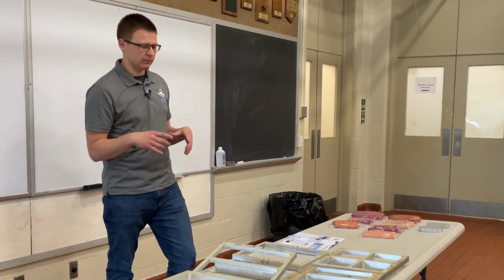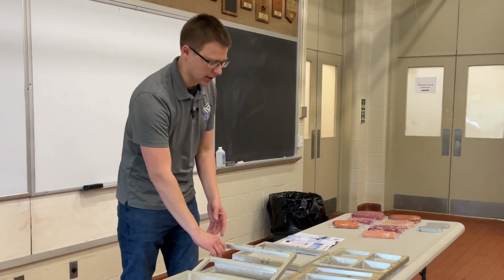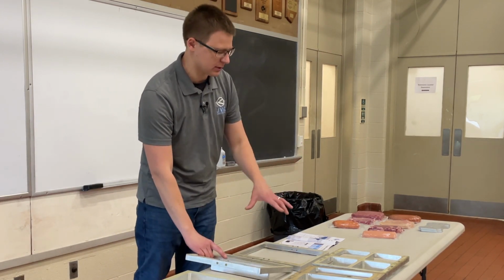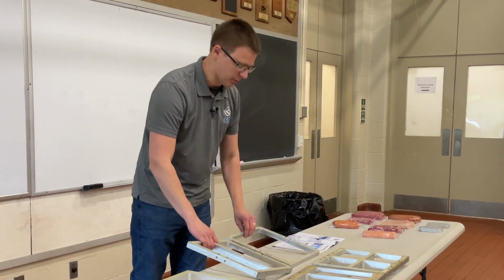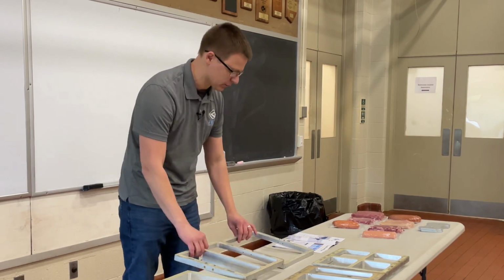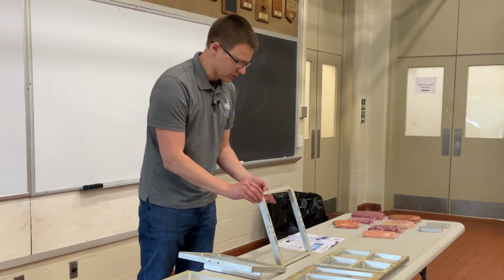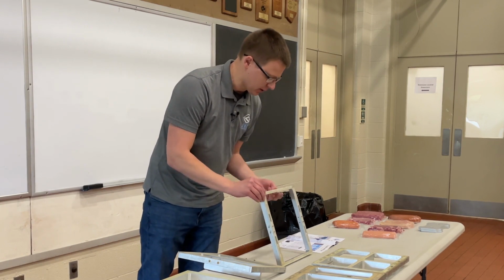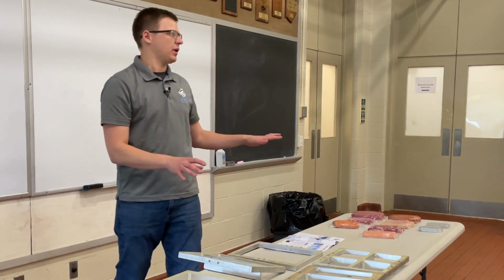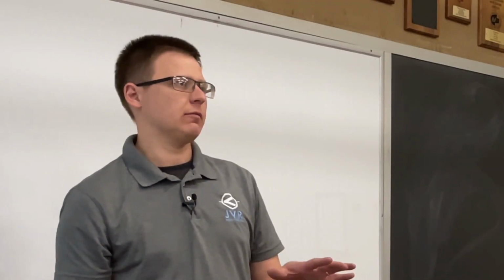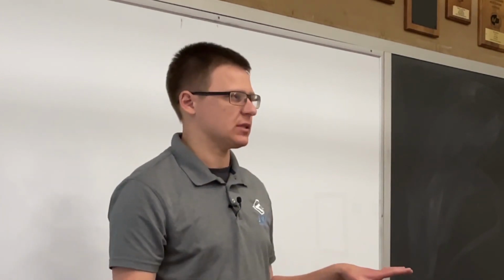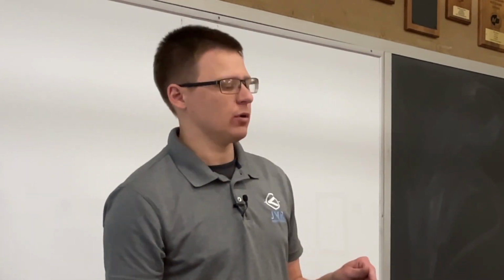So let's say your sales guy is quoting you on this setup, this size machine, and they say, oh, these two pockets are what you need for your products. Well, they'll give you drawings with inside dimensions here. Actually draw that out on a piece of paper. The product has to fit in there. You can't force products in there. It can't bulge out the sides. You'll run into issues.